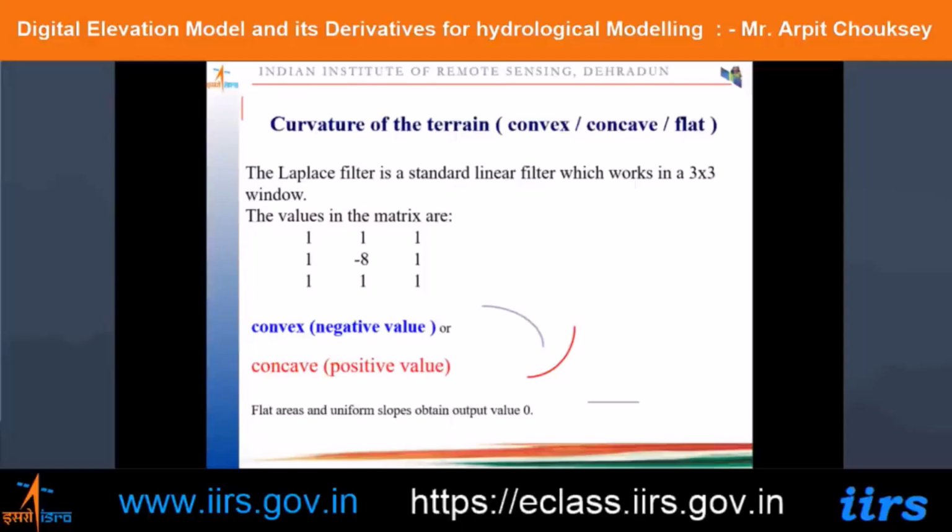So first is the compound topographic index, also called as the CTI. So it represents the tendency to accumulate water of a pixel with a low slope angle is greater than one of a very steep pixel. So it shows the tendency to accumulate water. It is very commonly used parameter to describe this tendency. CTI is equal to logarithmic of AF, that means the flow accumulation or the specific catchment area draining through the point, divided by tangent of beta. And it is also called sometimes as topographic moisture index or wetness index.